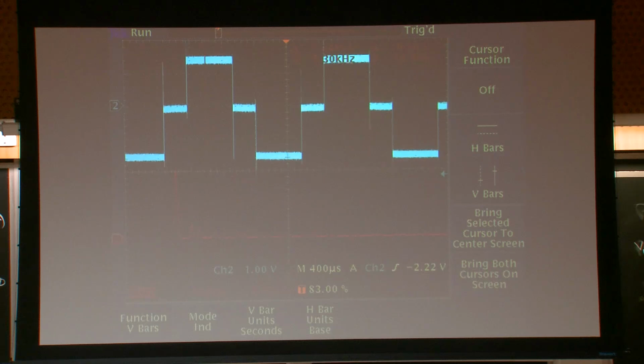At the bottom, we are looking at the FFT of the voltage waveform, so the voltage magnitudes at different harmonics. If I move my cursor to the first spike, it's really hard to see, but you can see on the top right that it's happening at 600 hertz, which is our switching frequency, the fundamental.